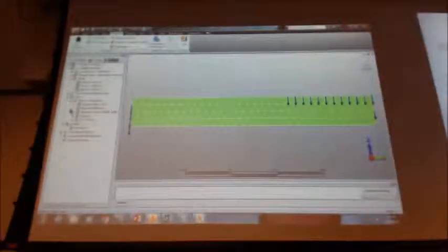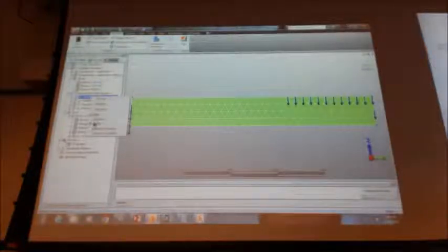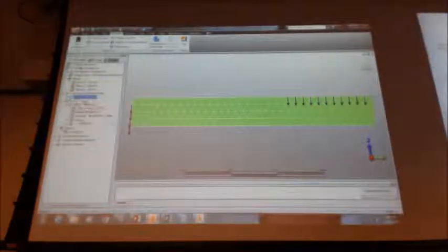Okay, notice where my loads are and my constraints. Now look what happened to my loads and constraints. So anytime you change the mesh, you're going to have to go to loads and constraints and delete them. Do we not have an option to use like a distributed force? I am not aware. No, because if you set it up as a beam and then try to do it, it doesn't adjust it to him. So you actually have to go with the file.